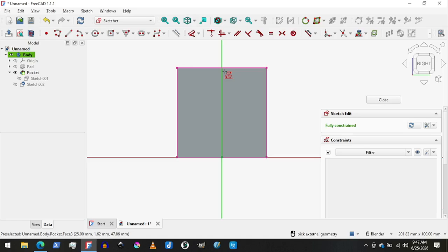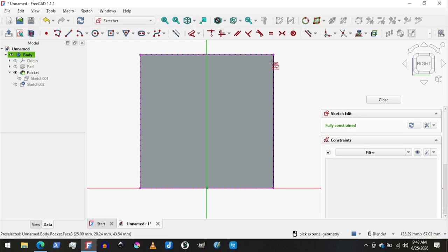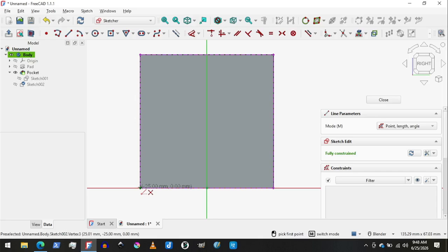And this time, instead of typing a dimension, I'm going to say go up to a face. What this does, when I select it, I rotate around and tell it, I want you to go until you get to this. Now, if I change the size of the cube, it would keep going until this face. I'm going to go ahead and do this last one here. So I switch to construction lines. Then I switch back to real ones, set to 25.